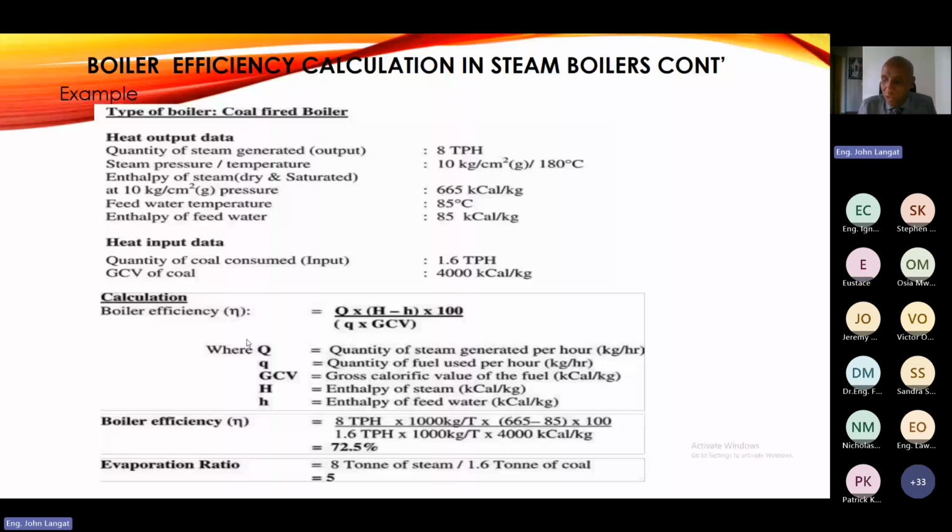As I said earlier in my presentation, you cannot use the condensate meter as a steam meter. The readings from a condensate meter are not an indication of steam consumption in your organization. The operating pressures for the two are totally different, and the specific volumes for steam and for condensate are totally different, so you're not going to get the same. So the best thing is to install a steam meter.